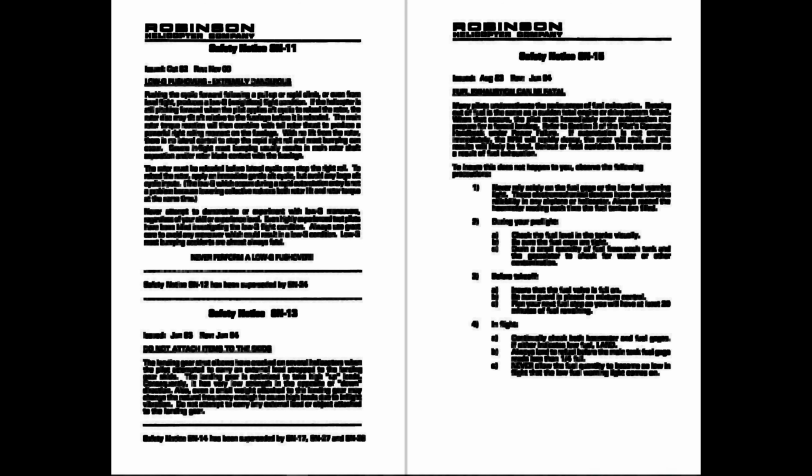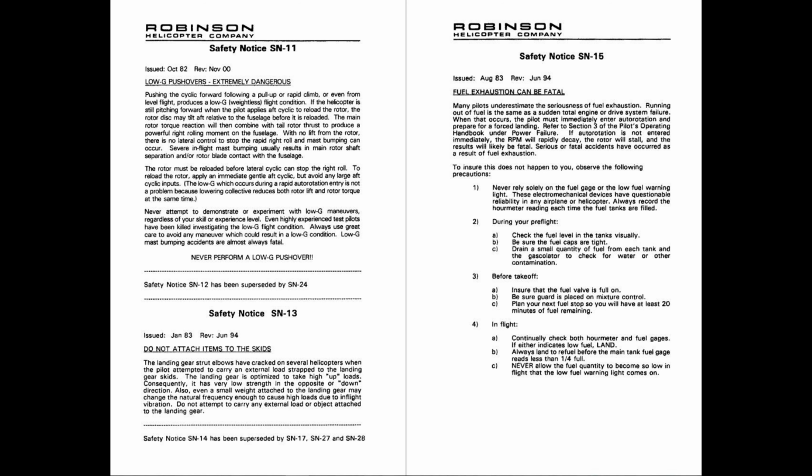What might severe mast bumping cause? Severe mast bumping might cause the main rotor shaft separation and the rotor blade to make contact with the fuselage.